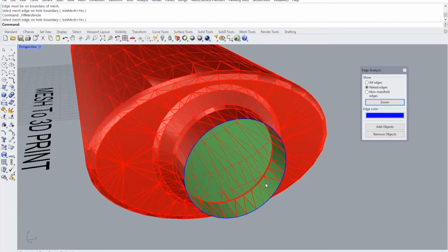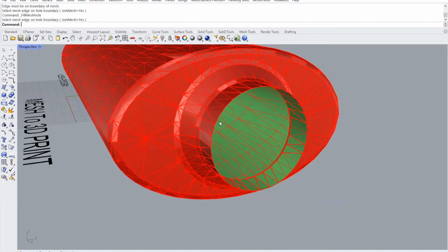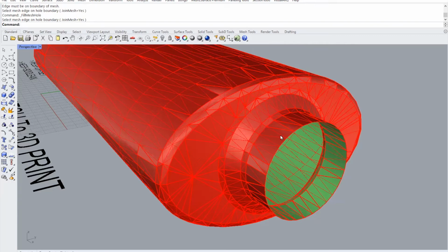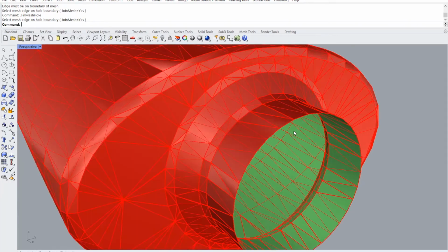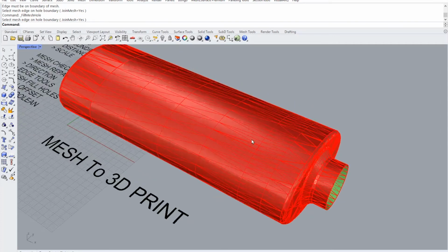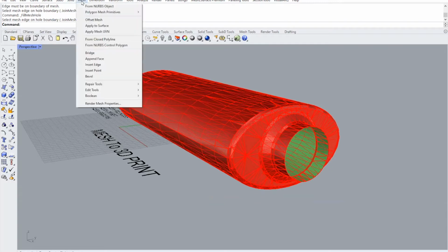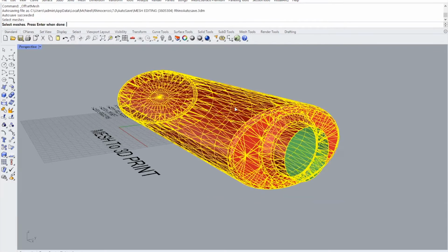We'll leave this vacant for a while because we're going to offset the mesh, give some thickness. So we'll close that command. Currently what you're looking at is a piece of very thin wall, paper thin wall. So it requires certain thickness. We're going to offset mesh to make this a valid print. So I'm going to use mesh, offset mesh. I'm going to select the bottle.